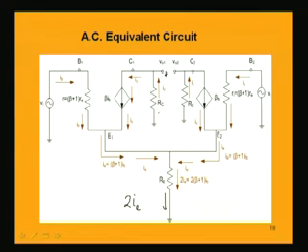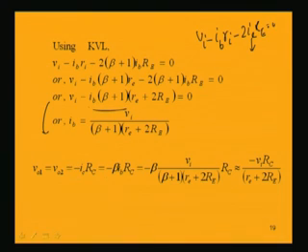Polarity of this voltage is plus with respect to ground. Current is flowing from bottom to top with a drop with this polarity plus to minus from bottom to top. So, it is opposite, V01 is minus IC into RC, and here also same case. So, we get that is equal to minus IC, which is nothing but beta times of IB into RC. We can replace beta IB from the previous expression. So, we get minus beta into Vi by (beta plus 1) into RE plus twice capital RE, into RC. So, approximately we can write, after assuming that beta is equal to beta plus 1, this is approximately equal.